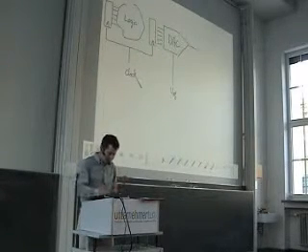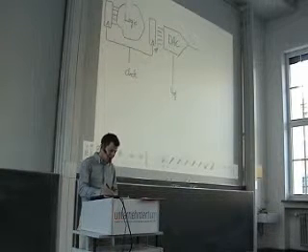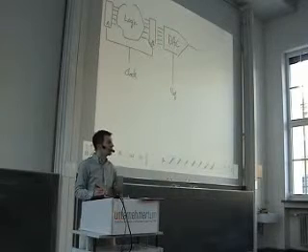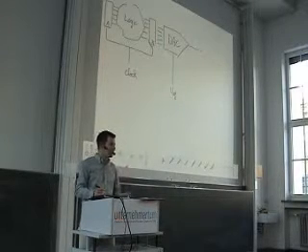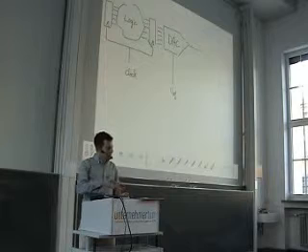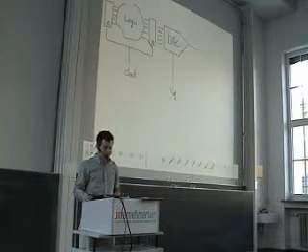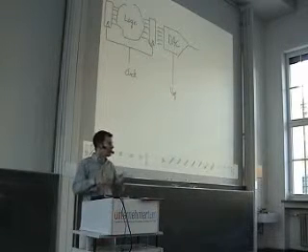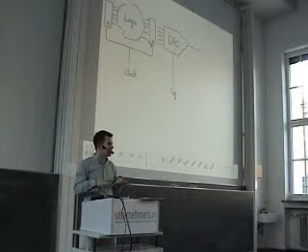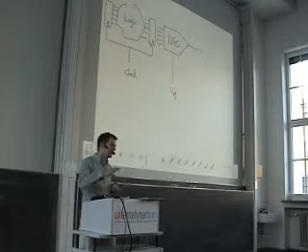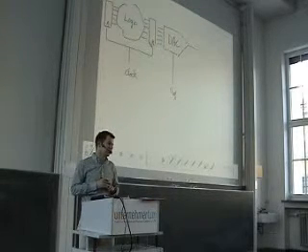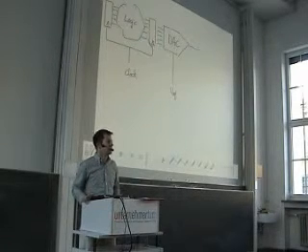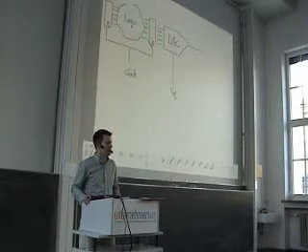And then these signals switch at the same time. They are synchronized to the clock. The clock signal occurs, all signals switch, and the DAC creates the correct output value. There are still some challenges, because if you distribute the flip-flops for the various bits, you have to assure that the clock signal arrives at them at the same time, but this is a straightforward design challenge. In principle, you have solved this issue here.